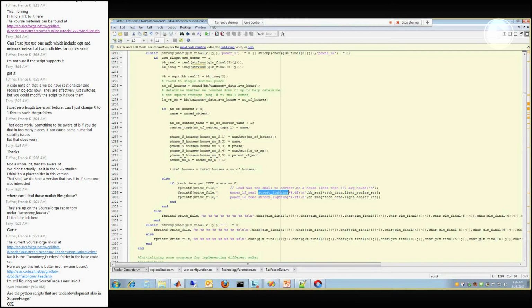And the reason you see some of these 10 or 100-watt loads is, one, they may be actual loads. They could be something like a street light or a metered pump. But often they're artifacts of load allocation studies.